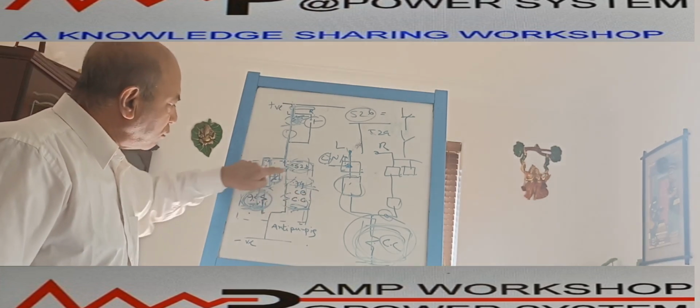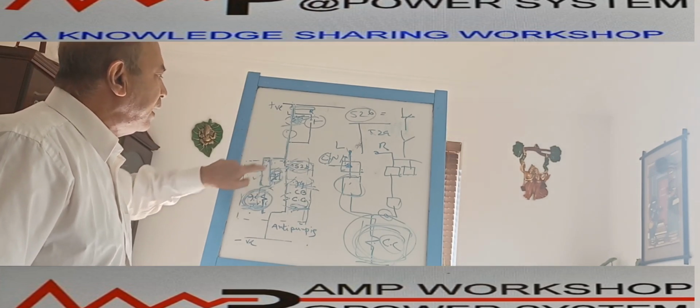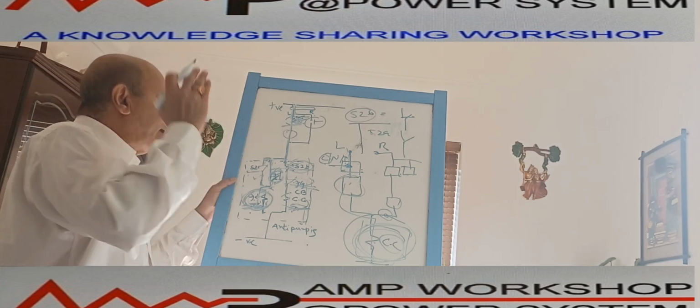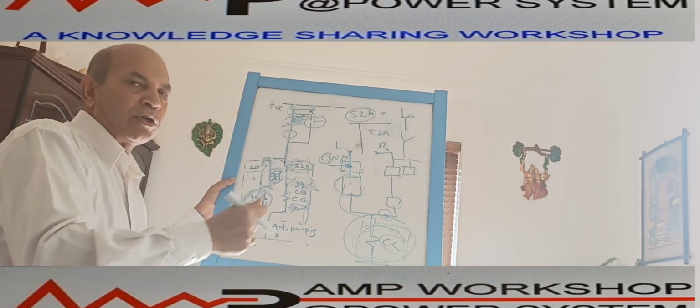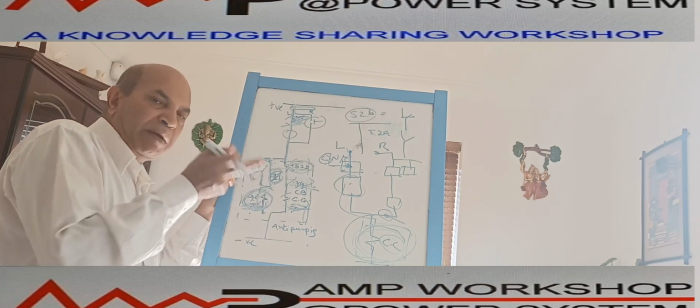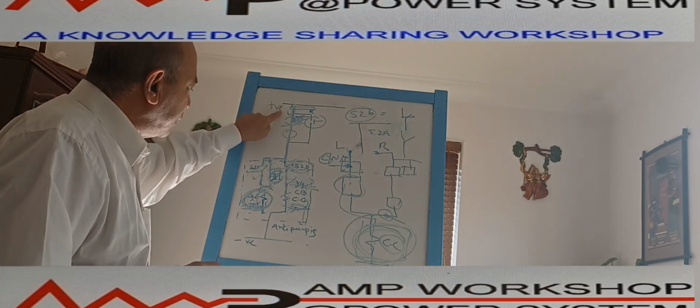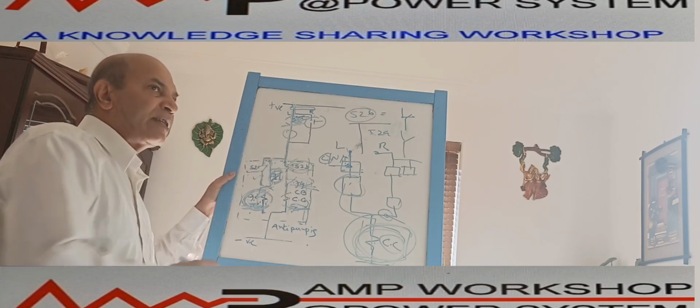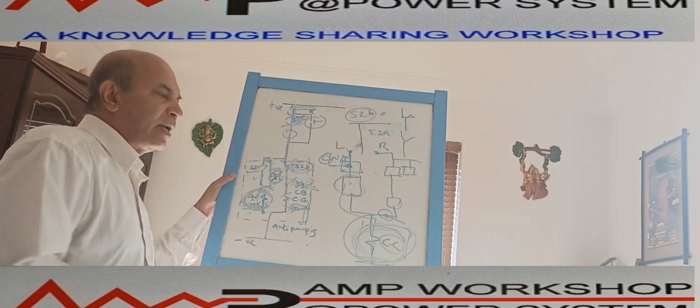So this way, this anti-pumping relay, this 94 relay, is preventing multiple closing and tripping operations. Inadvertently, if somebody maintains the closing command and there is a fault on the breaker at the same time, the breaker will close once, then on fault it will trip, and it will not close further, because the anti-pumping relay will prevent that closing. Also, if somebody tries to maintain this closing command continuously, which can damage the closing coil, that is also prevented by the anti-pumping relay. So these are the basic features of the anti-pumping relay, and that's why we use it in the circuit breaker.